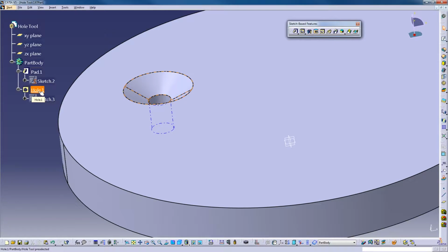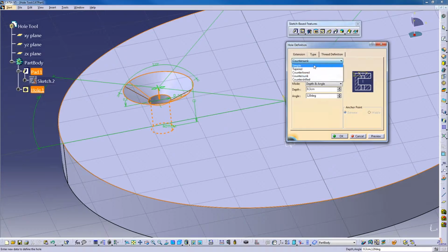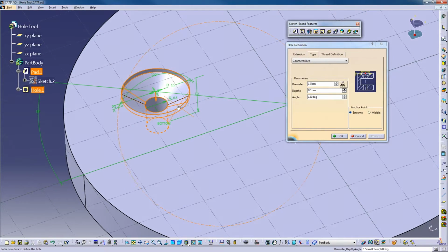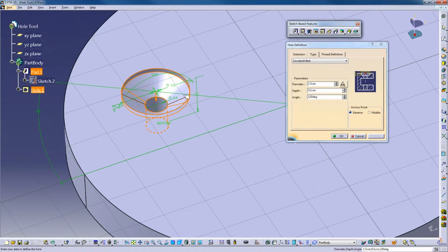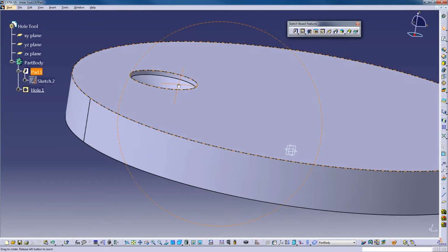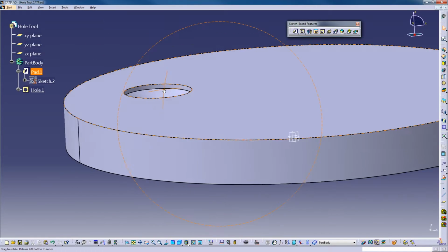What I do is, even if the fastener itself is just plain countersunk, it doesn't say it's counter drilled, I make pretty much all of my holes for countersunk fasteners counter drilled, and I'll say the depth here might only be maybe 1 millimeter, right, just like that. But if the diameter of the head is 1.5 centimeters, I'll drop it down just that tiny little bit there, just so I can get the fastener to go in perfectly flush.